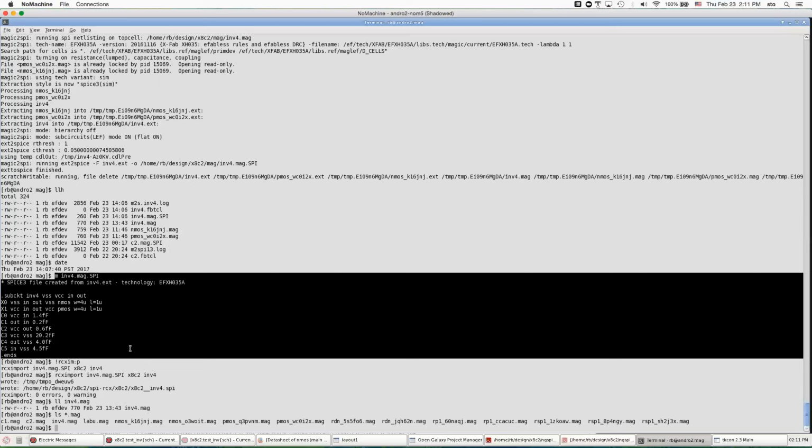I mean, essentially, we have two flows that are completely separate from each other. But from an abstract point of view, both of them should be the same, because one is Magic schematic to SPICE deck, the other one is Electric schematic to SPICE deck of the same circuit, right? Well, we hope they're the same, and until you run LVS, you don't know that they're the same.